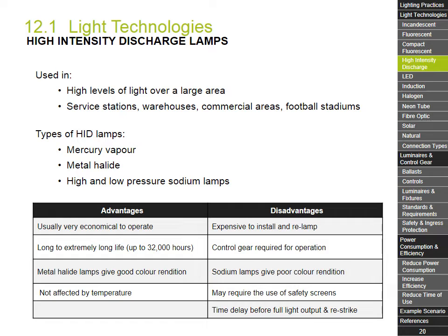There are a few types of HID lamps, and depending on the lamp, they produce different characteristics. Some have higher light intensity and correlated color temperature, whilst others boast high CRI, life expectancy, and efficiency. Metal halide lamps are common and used when normal color appearance is required, such as television production. Mercury vapor HID are not as common now as metal halide.